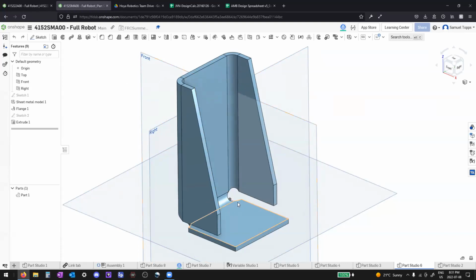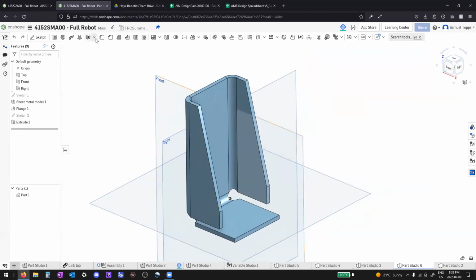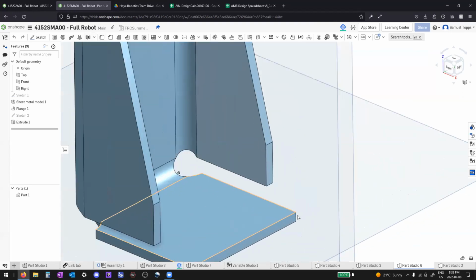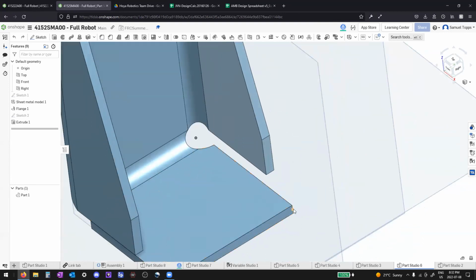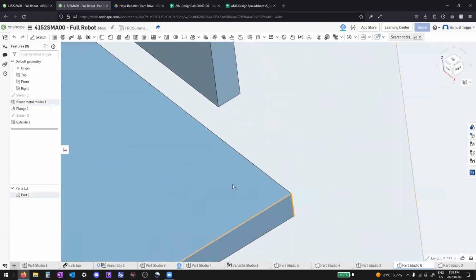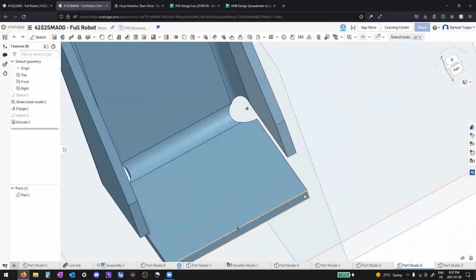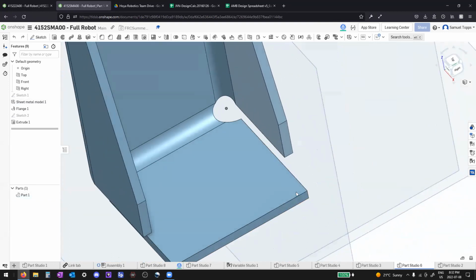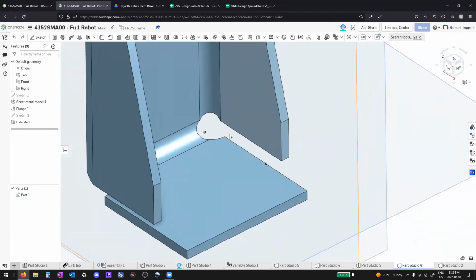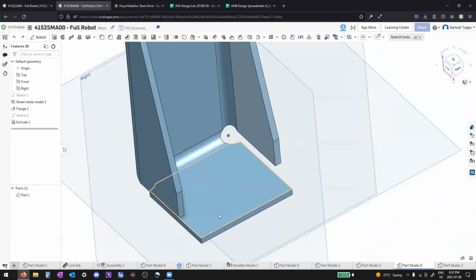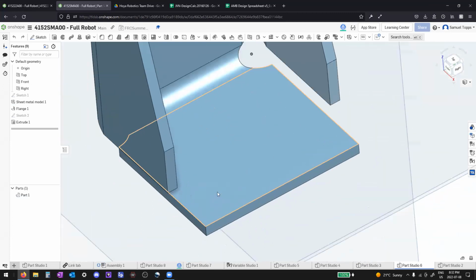Similar to the simulation question earlier, when you're thinking about how strong a part is, generally the weakest points are going to be hard corners. Those are stress concentrators. All the stress will be built up right on that sharp point, and those sharp points are likely where you'll see it fail. So maybe it's here, there, over here. If I had some holes here to mount it, you might find that the crack went from a hole straight to a corner.